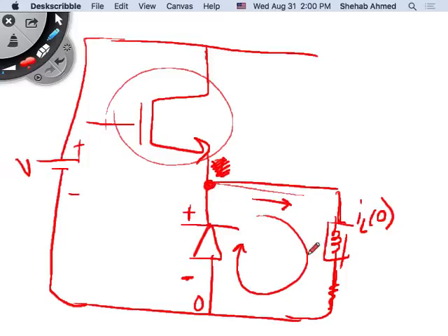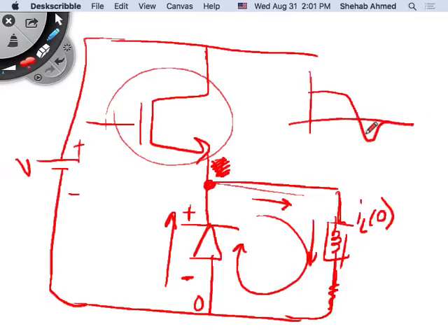And what is the condition that is forcing the diode to be on? It's the current, the inductive current that's flowing through here. It's a circuit that is forcing a current in a certain direction. So the diode will turn on and conduct again, right? If that's the case, what was happening? We talked about reverse recovery. The diode's on, and then before it goes off, there's some time when there's a reverse recovery, when there's current still flowing through it. If current's still flowing through, that means it's like a short circuit.